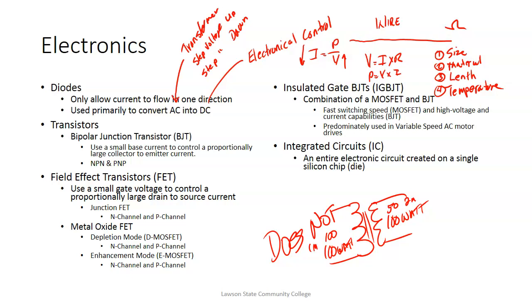to provide that same power. So if you're thinking about, okay, in DC we learned if voltage goes up, current goes up, but that's applying to the load. What I'm talking about is trying to get the power to your load. So this is the source. So that means if I can step my voltage up to 750,000 volts, I could send 750,000 watts of power with 1 amp of current.